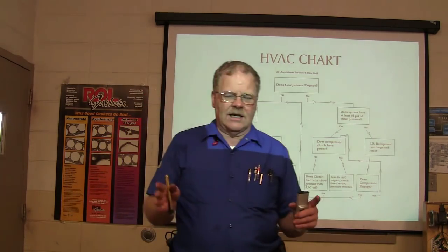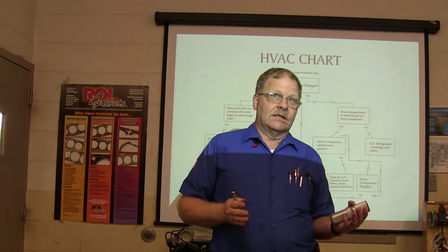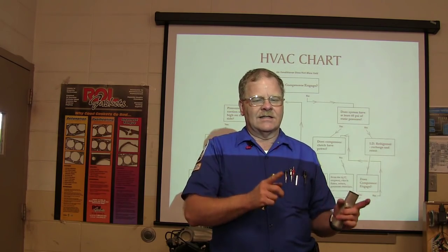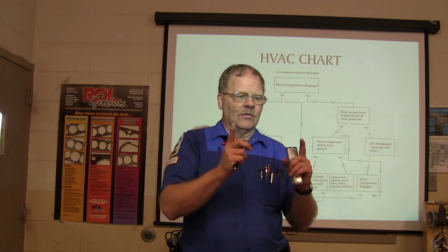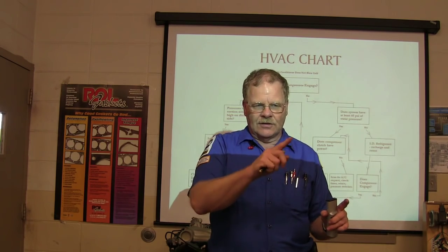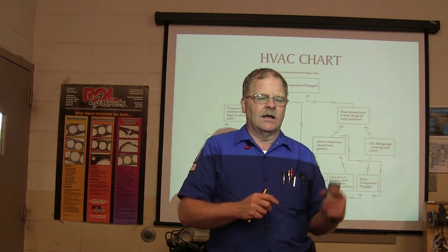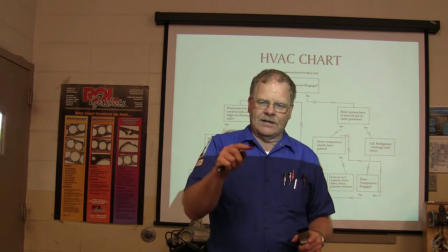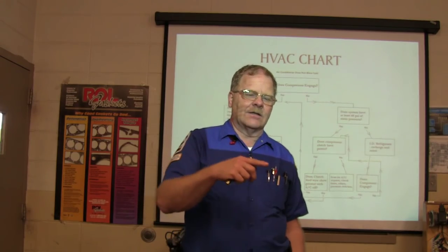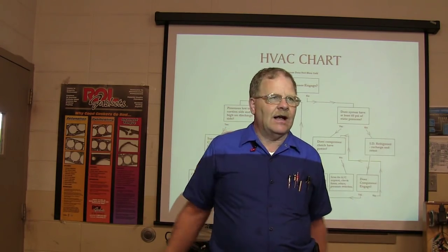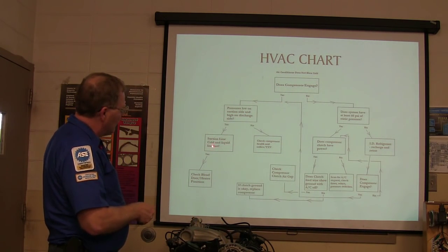So when you first plug in your gauges, you ought to see a static pressure. There's not any good book numbers on this, and they don't always tell you anything, but whenever you got a static pressure that's between 70 and 110, you're probably pretty well okay. I have seen it have like 90 pounds of pressure on both gauges. Of course, the gauges are scaled different, but if you look at the numbers, they're going to be equal whenever the compressor hasn't been running. When the compressor kicks on, the low side ought to start dropping down to close to 30, and the high side ought to be up around 150. In this cold weather, it's going to short cycle and everything, because the ambient temperature has everything to do with how the refrigerant responds.